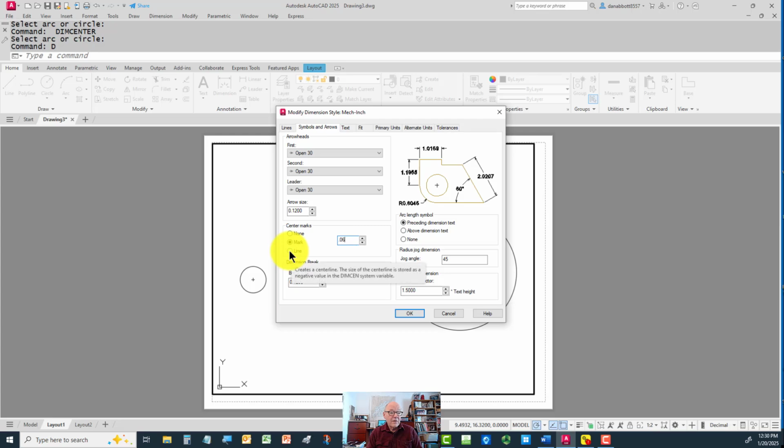By default, I want lines placed, and those lines would be extension lines. Now, the AutoCAD center mark tool, the new one, which is so bad because the center mark changes size, has extension lines by default, but we don't want to ever use it. We want to use AutoCAD's old-fashioned center mark tool, the DIMCEN tool. This size is going to give me the size that I want, and I want it to draw lines only when I place a center mark.